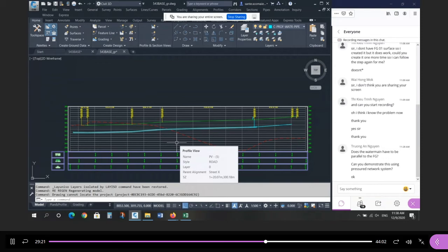If you change the slope in the drawing because you have to go underneath or above another pipe or a structure, then you have to go and update the slope on the spreadsheet and see if the pipe needs to be adjusted, right? So if you make something steeper, you might be able to make the pipe smaller. If you make it flatter, you might have to make it bigger. And that's the bit of back and forth.